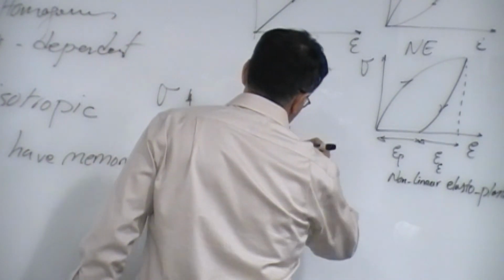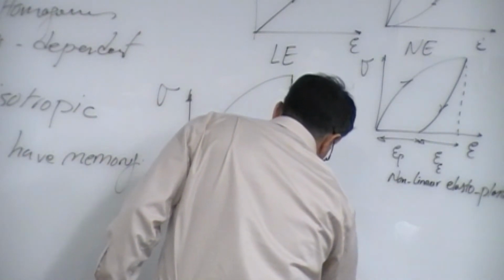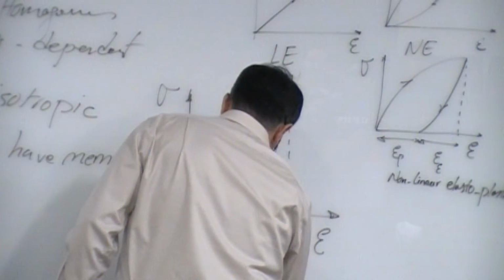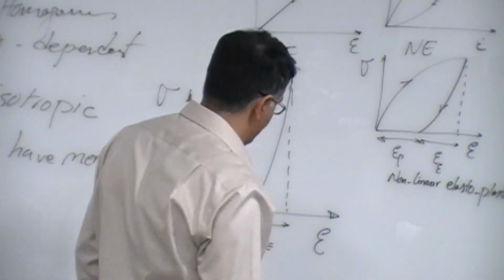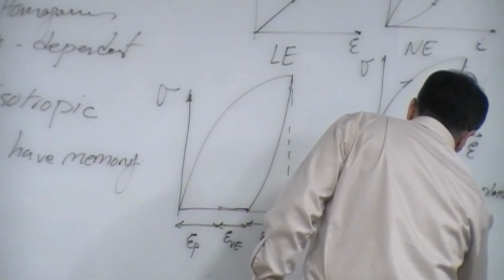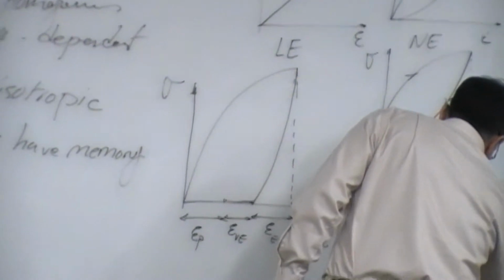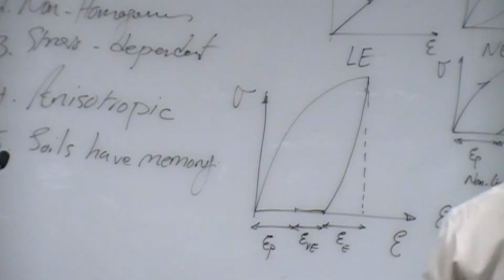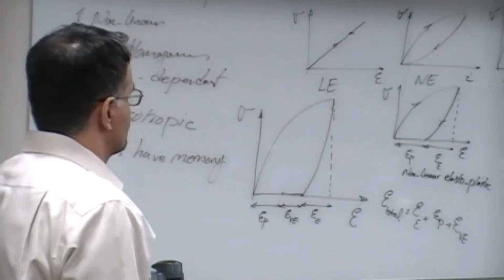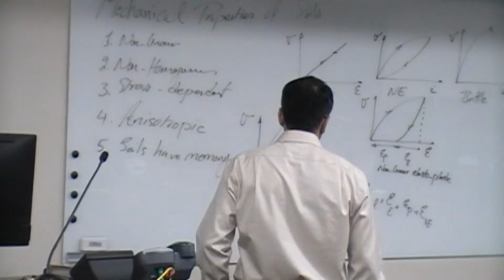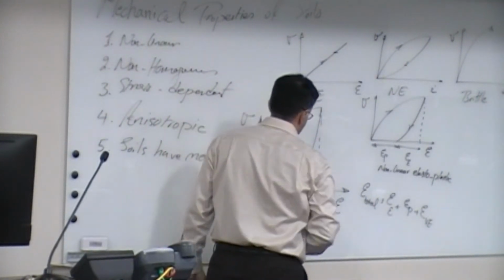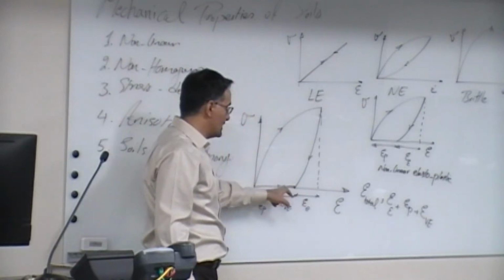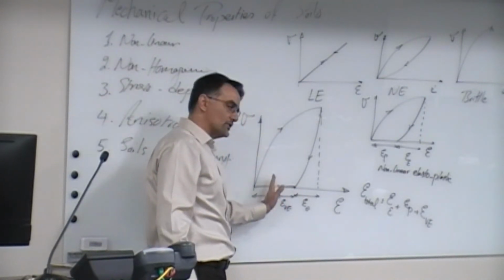Can you tell me what kind of material I am dealing with? I applied the load, went all the way to here, removed the load, came back down to here, and then it took some time for a portion of it to recover, and then a portion of it stayed in the material.